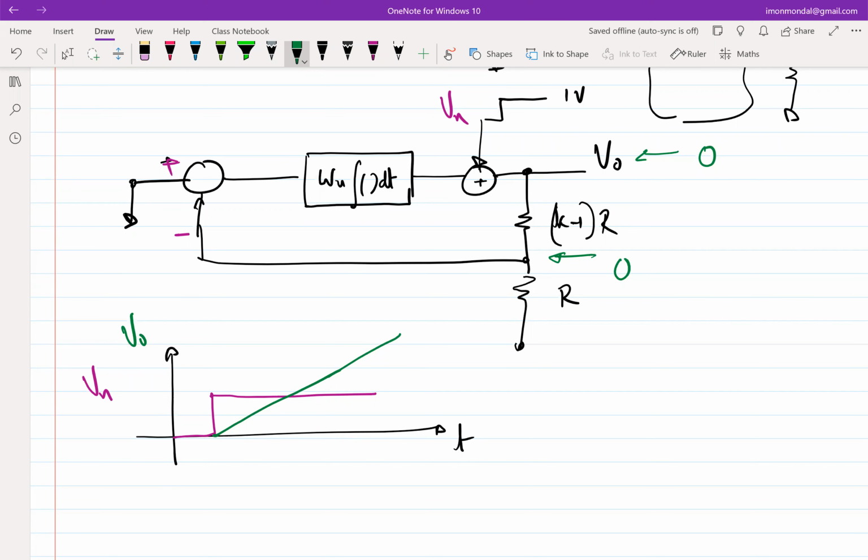We'll do the step thing also, but let's assume that we have waited infinite time and the loop has settled. I think the slope of the ramp will be negative, right? This 1 volt is getting divided through the resistor divider, and there is a negative side. The error voltage will be initially negative, so the slope will be negative. What will happen after infinite time? It's easier to figure out what will happen at DC, and then we can work out the dynamics.